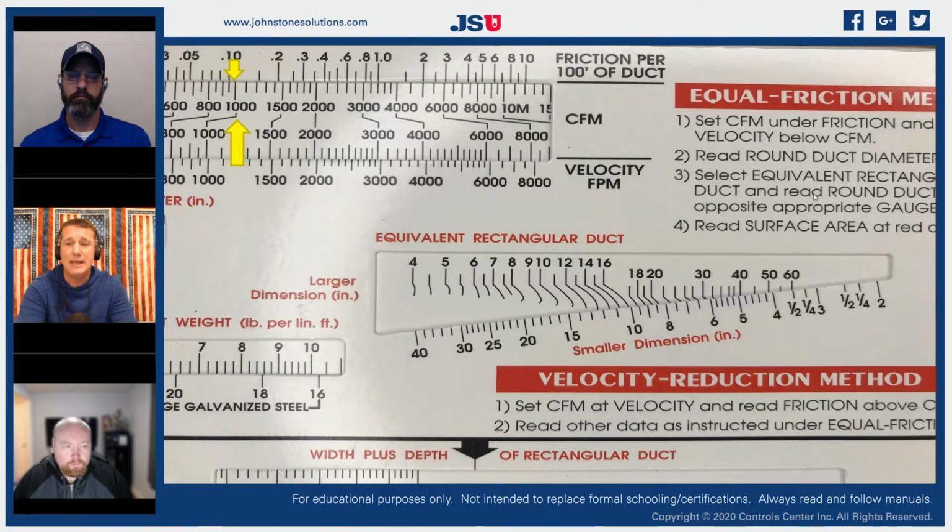If I wanted to make a custom duct, so maybe I was trying to get through a space where a standard 8-inch or 10-inch isn't going to fit. Well, all I have to do now is figure out what else do I want it to be. I could be a 10 by, so that's slightly over 16. So I need to be slightly over 16. So 10 by 16 and a half. Or I could do a 5 by 40.